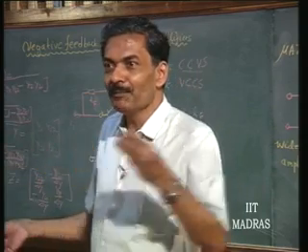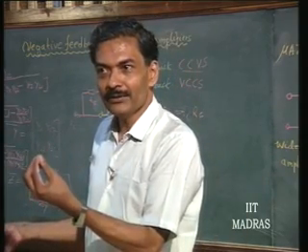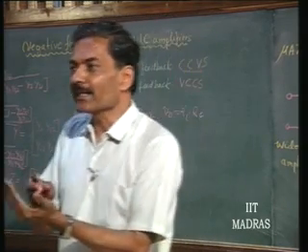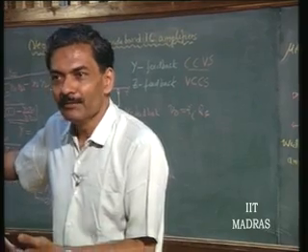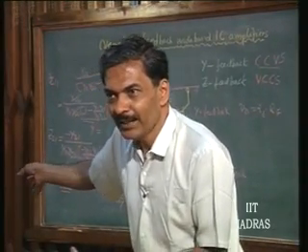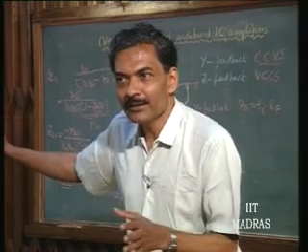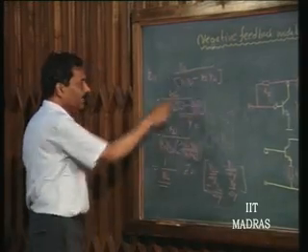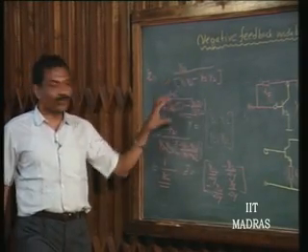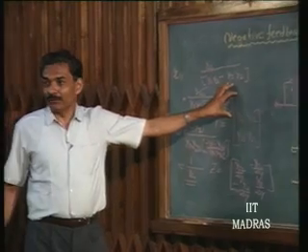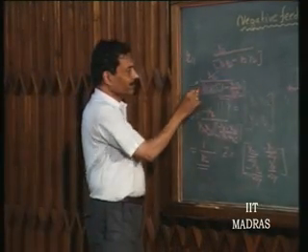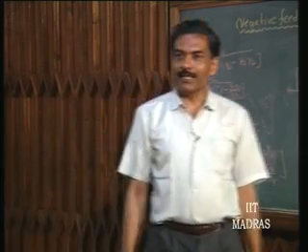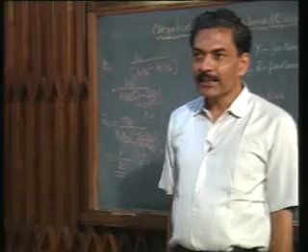Since y12 of the amplifier has gone down to very close to 0, or is very small, even at very high frequency, the bandwidth improvement factor comes simply because of desensitization itself, okay. Is it clear or not? And if you do this similar thing here, if the loop gain is very high, it is the loop gain which makes this go towards 0, because these things will get cancelled, and it is the y12 y21 product which will make it go towards 0, which is not getting cancelled there.